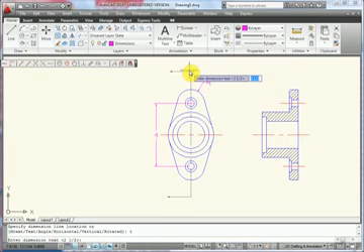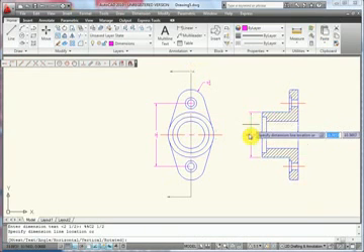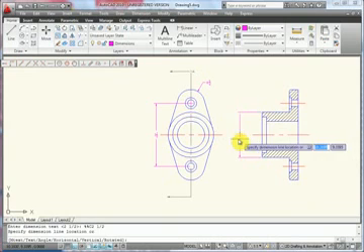We want the 2.5 to stay there, so I'm just going to press the left arrow to unhighlight it and enter a %% which stands for diameter. Press enter to finish, and now I need to still select the location for this, which I'll place right there.